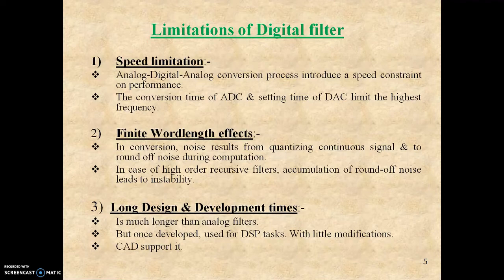Second limitation is related to finite word length effects. Digital filters are subject to analog to digital conversion noise resulting from quantizing a continuous signal and to round off noise occurred during computation. With higher order recursive filters, the accumulation of round off noise could lead to instability.